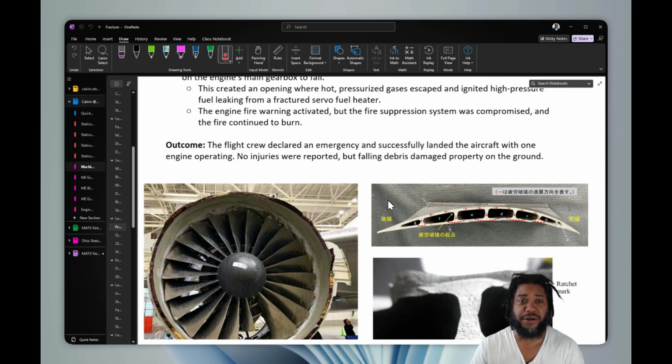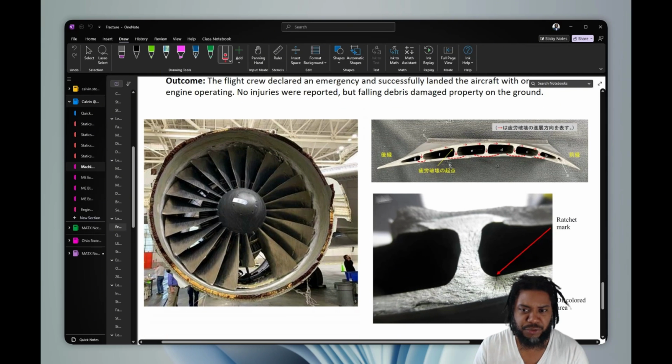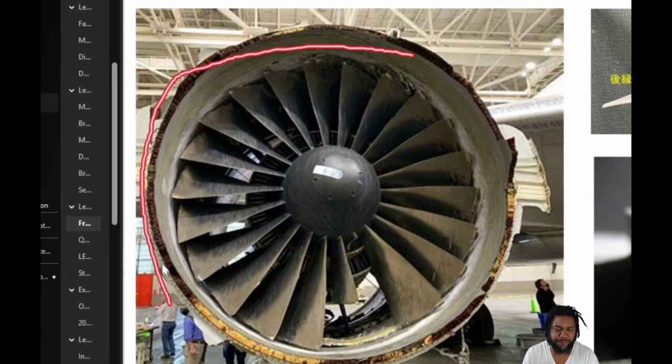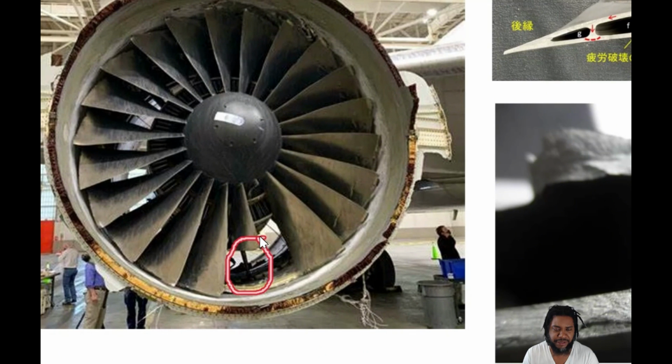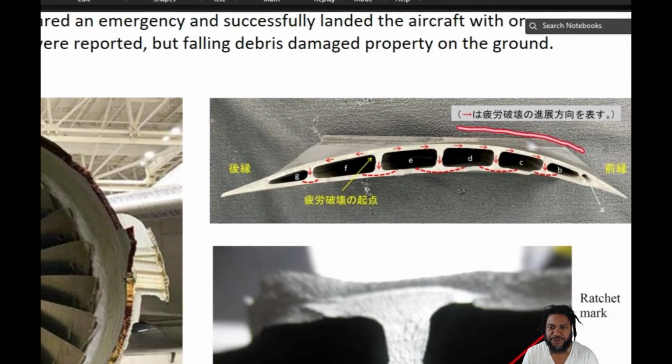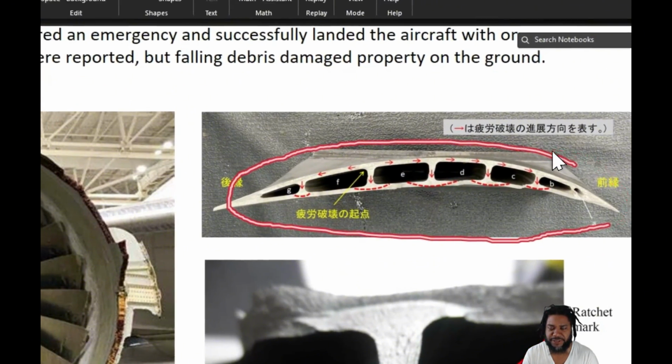So this is a case where, in damage tolerant design, if we do not maintain proper inspection intervals and inspect any component that might exhibit crack initiation or growth of a crack, then we can have these catastrophic types of failures, these very, very dangerous failures. So below here are a couple of images. Here is the engine in the study. We can see this is the fan blade that sheared off and failed and impacts the housing. This is the actual residual blade left itself.